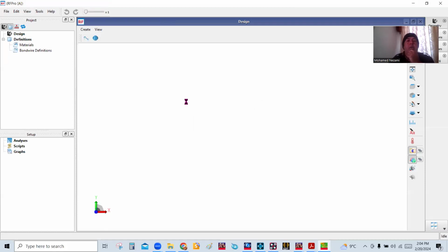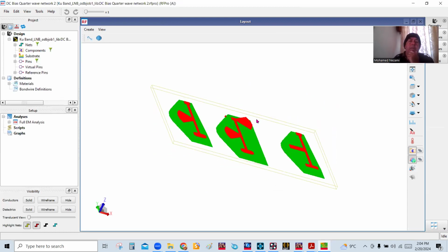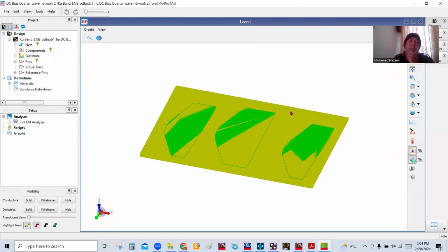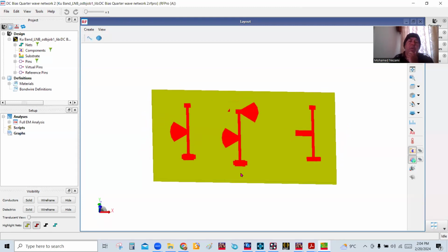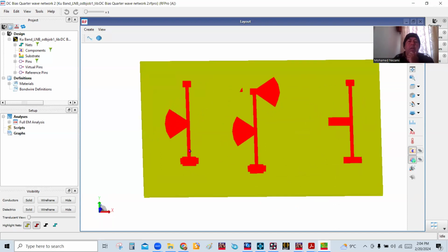So we're going to analyze all of these and look at them. Okay, so here's my design, and let me solidify the substrate. This is the bottom copper shown. Everything is fine. What I'm going to do right now is look at the frequency response from this point to that point, and of course the insertion loss also, that's another criterion we need to look at.